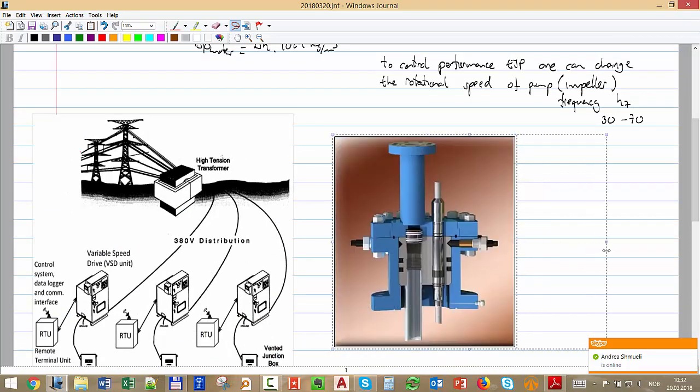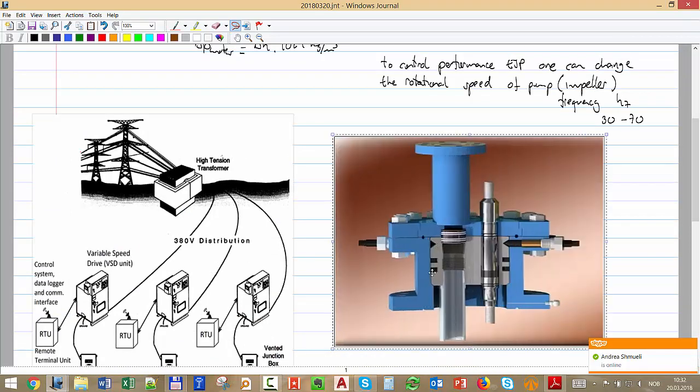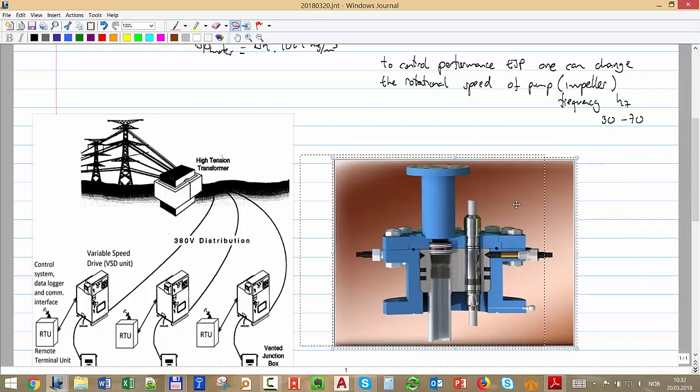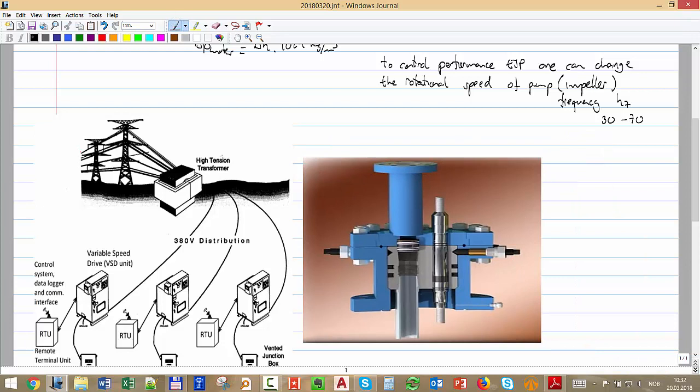Okay. You see that's at the wellhead. But then you have this part, which I always draw as a very simplistic drawing at the top. You have your surface production casing, then you have your tubing. Then you have the hanger, and also the seal that avoids any fluid from here going outside. Here you have your pump, but then you have to make a hole here.